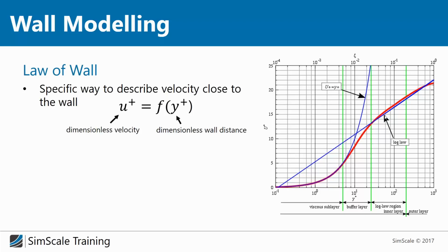If you take a look at the beginning, this is represented by this blue graph. It's a straight line in our logarithmic representation. Don't get confused. It's not linear in reality, but it seems to be logarithmic. And it means that inside this boundary layer, you can define different parts, different sublayers. There you have a viscous sublayer, buffer layer, and a lower region inner layer.